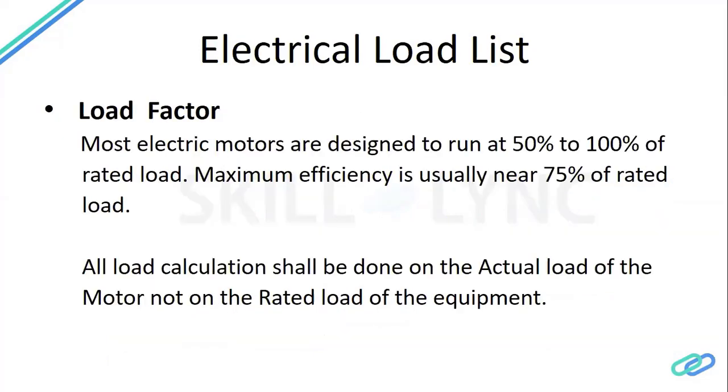Next is the load factor. Load factor is a very important thing. Say we are sizing a pump to transfer liquid from one place to another, and from our calculation, the required power comes to 32 kilowatt. But in the market, a 32 kilowatt motor is not available. In the market, motors come in standard ratings like 30 kilowatt and 37 kilowatt. So for a 32 kilowatt power requirement, you have to consider a 37 kilowatt motor rating. But actually the motor will consume only 32 kilowatt.